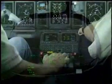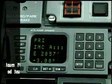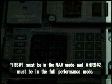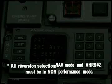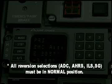The system conditions that must be met in order to achieve A3 capability include: IRS number 1 must be in the nav mode, and AHRS number 2 must be in the full performance mode. All reversion selections, ADC, AHRS, ILS, SG, must be in normal position.